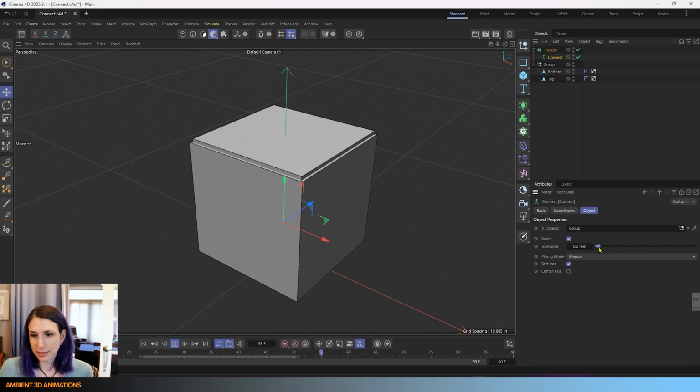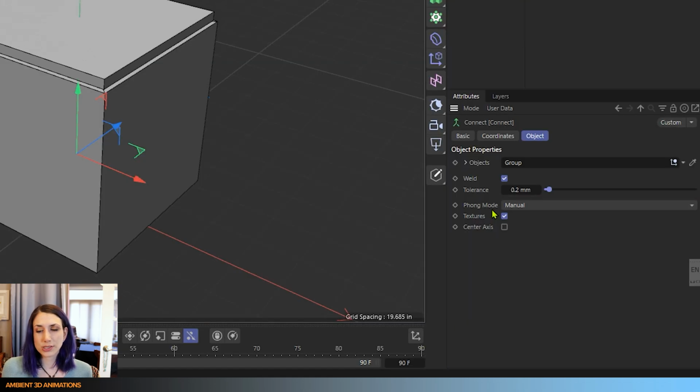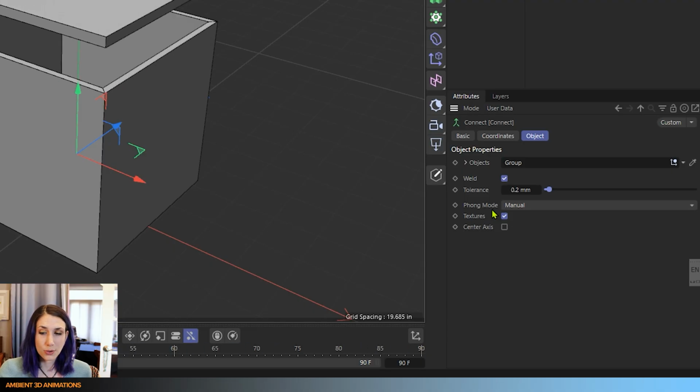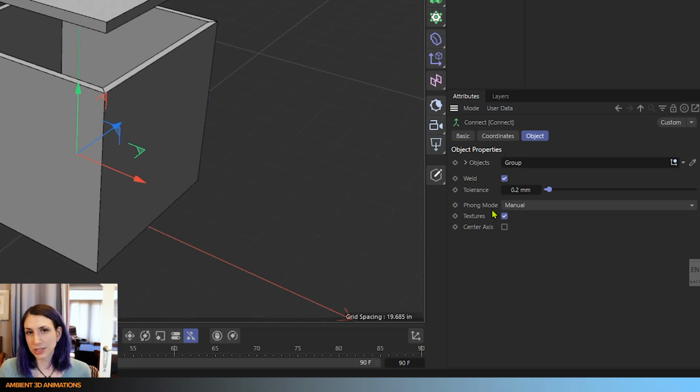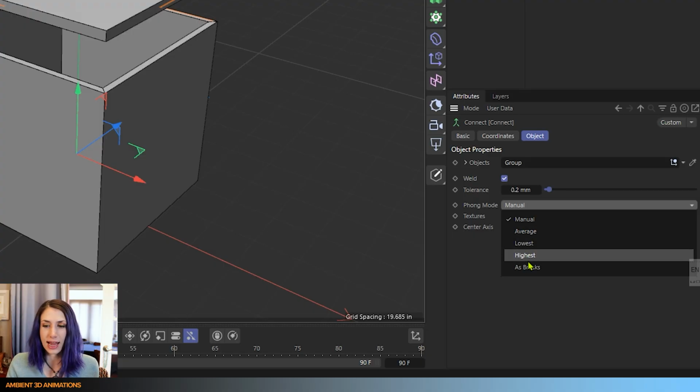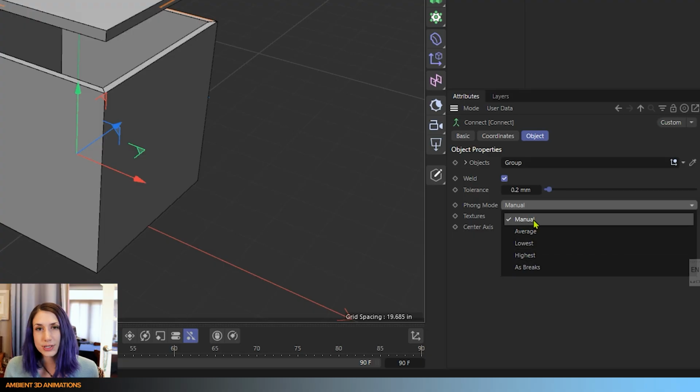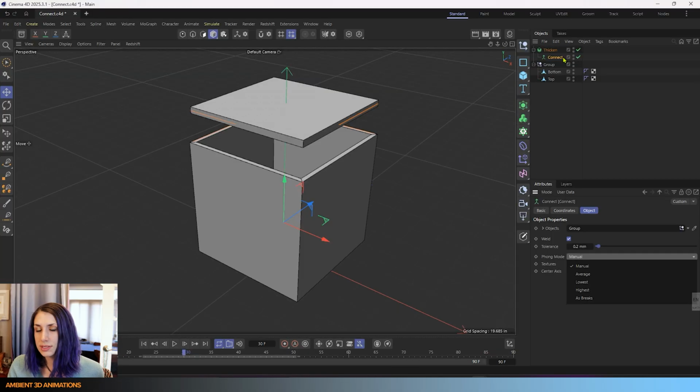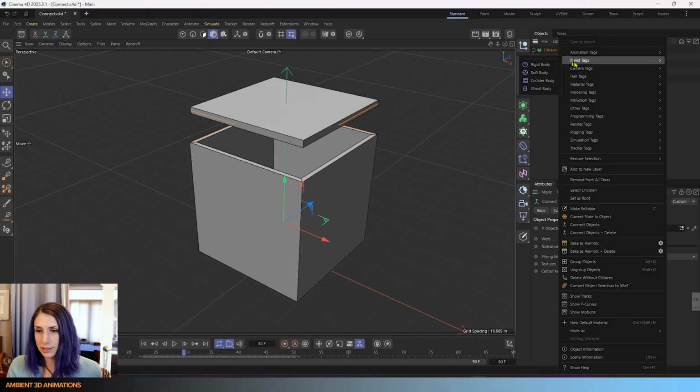So that's your tolerance. I'm going to move this back to some small number. You have different Phong modes. Now, if you want to learn all about the Phong tag and what Phong is, I actually explained that in a whole other episode, so I'll leave a link to that in the description. You have manual, average, lowest, highest, and as breaks. So the first one is manual, and manual is choosing to use a Phong tag added to the connect object to control the Phong.